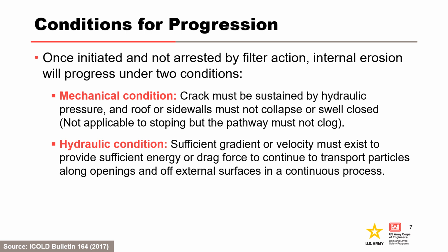Once initiated and not arrested by filter action, internal erosion will progress under a mechanical and hydraulic condition. For the mechanical condition, the crack must be sustained by hydraulic pressure, and the roof or sidewalls of a crack or pipe must not collapse or swell closed. A stable roof is inherently not applicable to internal migration and stoping, but the pathway must not clog.